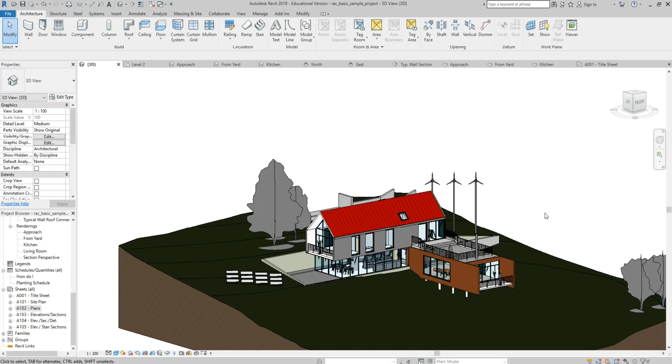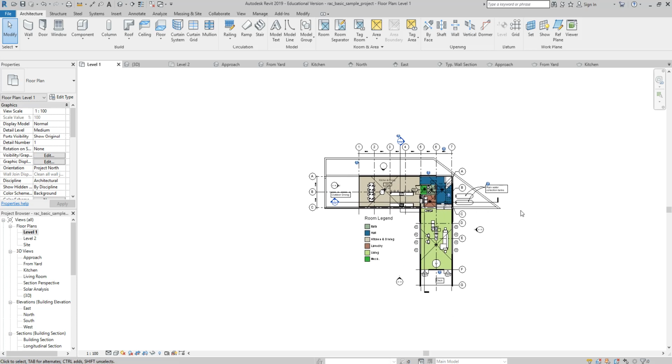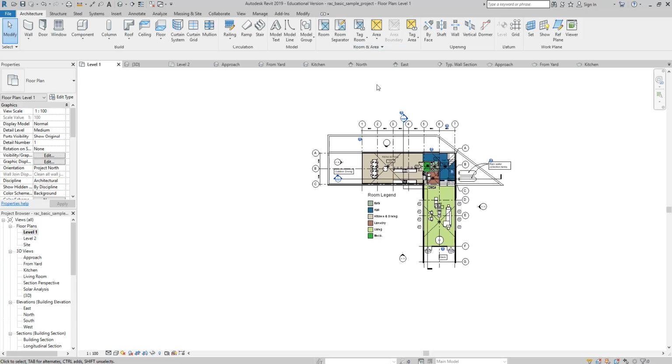Yep. Mm. Right. That's a good question, right? So when we talk about architectural elevations, this is the north elevation. So we are on the north side of the project. We're actually viewing south, but because we're on the north side, it's the north elevation. Facing the north side of the house. Right. You're on the north side of the house. Even though you're viewing south, it's still the north elevation because you're on the north side of the project. Yep, exactly. So it's north, east, south, west elevations.